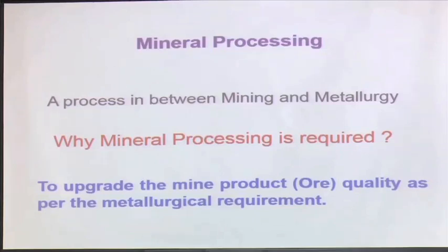Normally we have around 1% to 1.2% of copper in that, and I cannot directly put it into a furnace to extract it. The metallurgical requirement is that I must have a minimum copper content of 36.5%. Now, how do I enrich it from 1% to 36.5%? By some cheaper means. That is the subject of mineral processing.